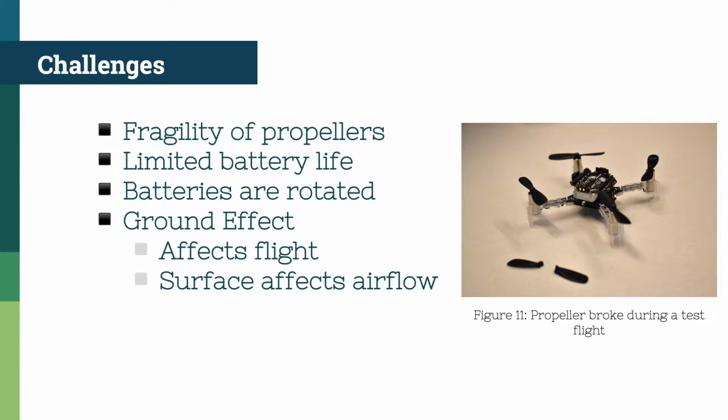And then the second and third issues are mainly because of batteries. Quadcopters are limited to a certain amount of battery mass that they can carry before the thrust they produce can't actually carry the battery mass that they have on board. So smaller batteries on drones end up meaning that you have less flight time, and our flight time was limited to 7 minutes, with a 45-minute charging period. So you can imagine that we would only be able to run a few flight tests before we ran out of battery and ended up having to charge. So the way we countered that was we brought several batteries, and then after they arrived, we would change them out for the batteries on the drone that actually went through flight tests, and then run flight tests continuously.